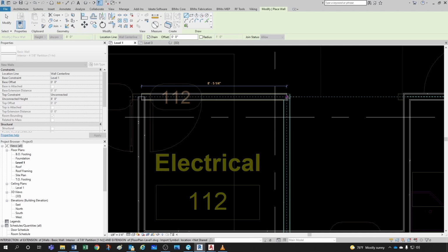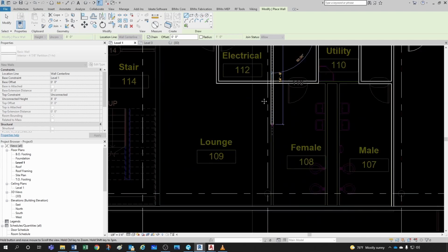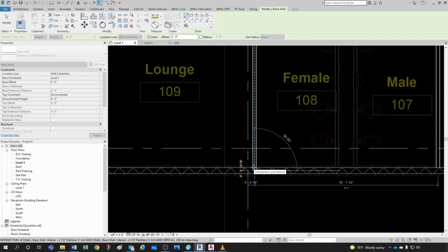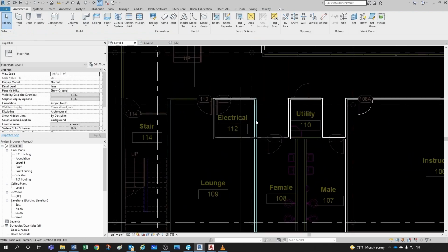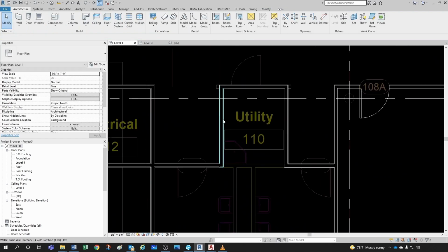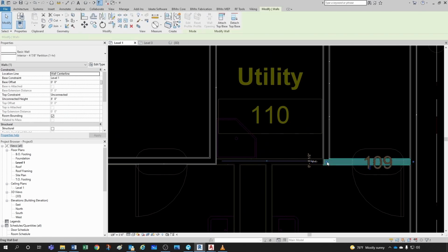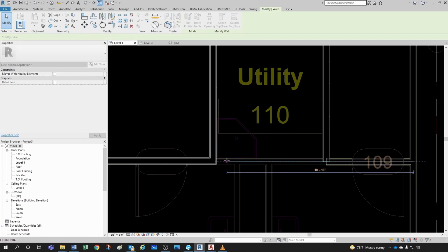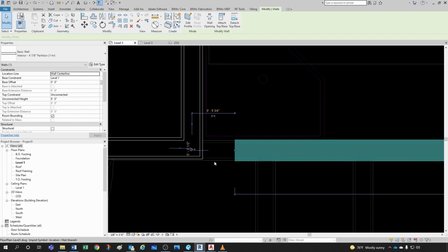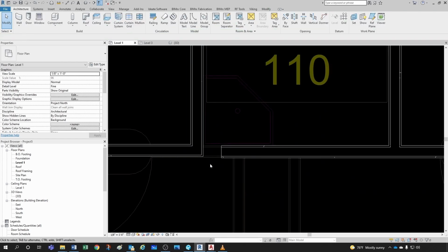So you can see how I'm kind of playing around, and just like that, I have a bunch of walls already created. So I can probably extend this. Notice that this wall here and that wall are not aligned. So I can do AL for align and then align that wall to this wall. And then I can do TR for trim and do something like that.